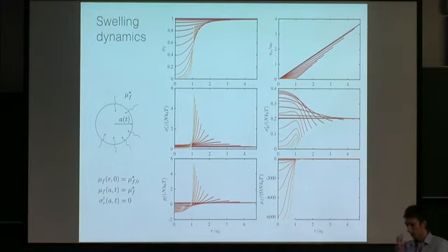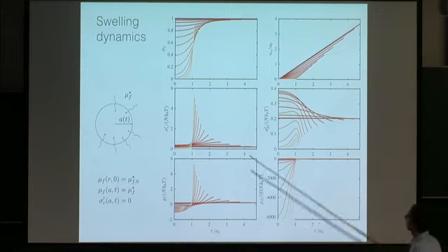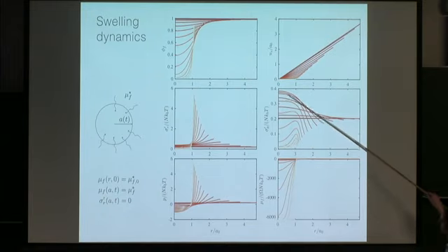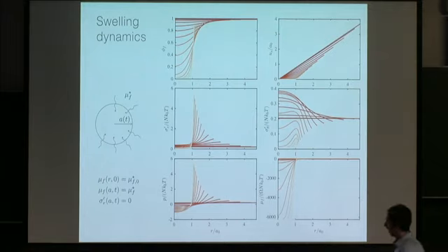And that one, well, let's say two things. So one is that it's complicated. And two is that it's non-monotonic, both in space and in time. So for example, if you think about the azimuthal effective stress, near the center of the gel, we start down here, it goes up to here, and then it comes back down to here. And so there's a lot of complicated things going on within the gel as the water content evolves. And in the interest of time, I don't think I'm going to talk more about the details. But of course, I'm happy to talk about it later.